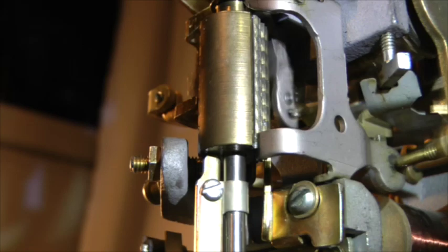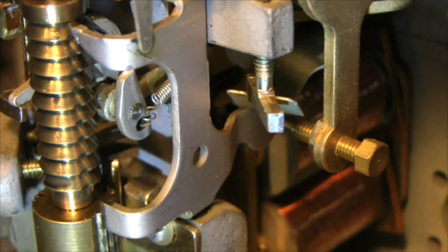As I mentioned earlier, in this position, the shaft is no longer supported by the stationary dog, and so the shaft drops down to its vertically normal position. This action causes the release magnet to be de-energized, which permits its armature to pivot back to its released position. The tension of the double dog spring then forces the double dog to pivot and re-engage with the vertical and rotary ratchets.